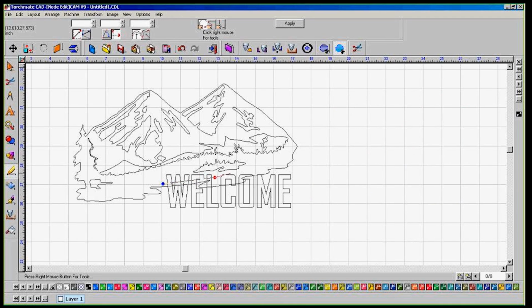Keep in mind that we can alter this blob or whatever shape you choose to make after the fact, but the whole ticket is to make sure that you come back to the original spot that you started out with, and once we're done with our shape, we can go ahead and press apply. How I know that my shape is solid and closed is I can go to View and put back Show Fill, and we can see that I have a solid shape out of what I just generated.